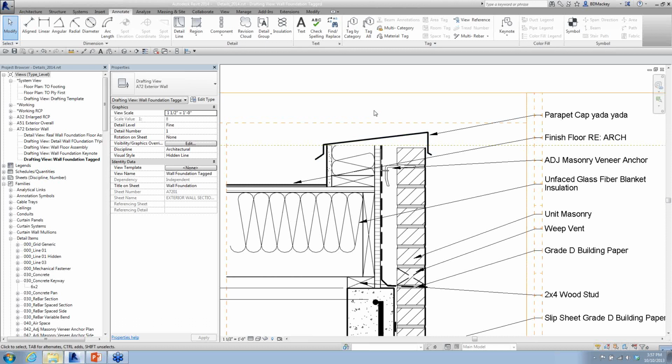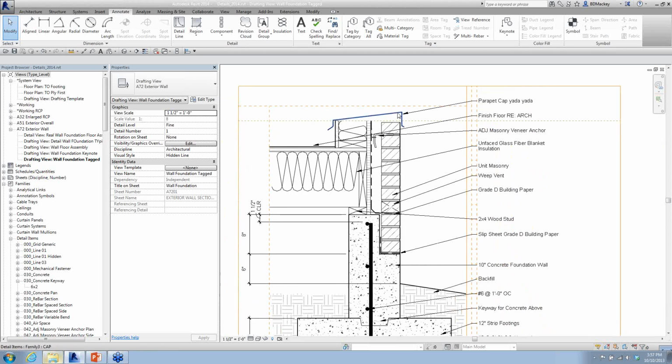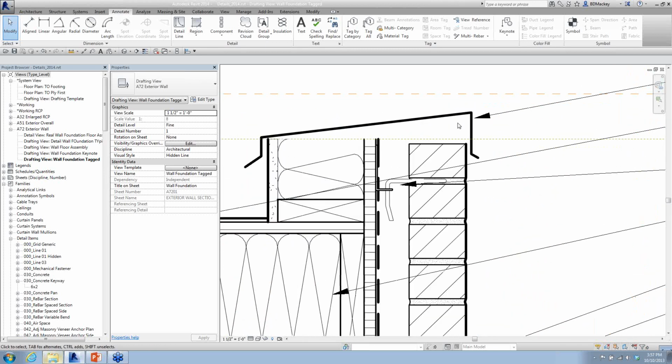Brian, how often do you use that copy and paste to go from a family to a project to a family, or, if you're in sketch mode, to take it in or out of sketch mode? I use copy to clipboard paste a lot. The question came up the other day: I'm creating a 3D countertop, and it's just a one-off countertop. How would I do that? Well, my theory is I go in and draw the floor plan, cut them to the clipboard, start a new family, paste them into that family, and now I have a family that's just that countertop that I can bring into the project. So I use that copy to clipboard paste quite often.